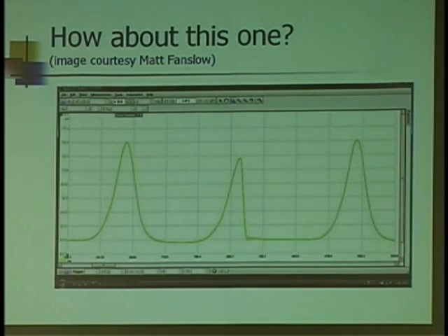And you're right, this exhaust valve is not opening. Remember that early relative compression with the starter? The low and the high? That's exactly what Matt had. And like any of us, he went after the low peak first.